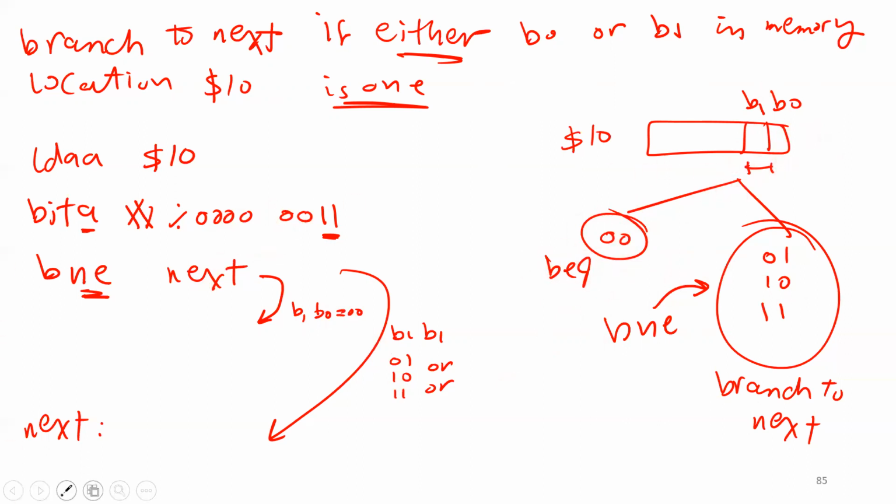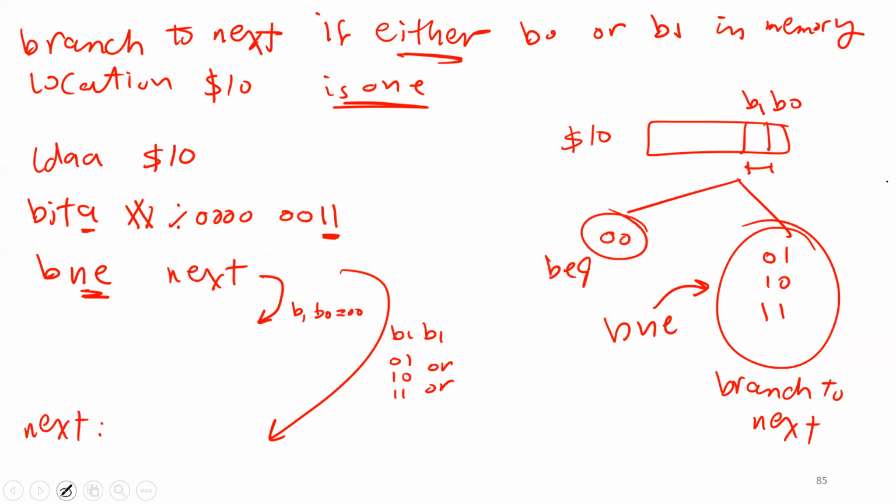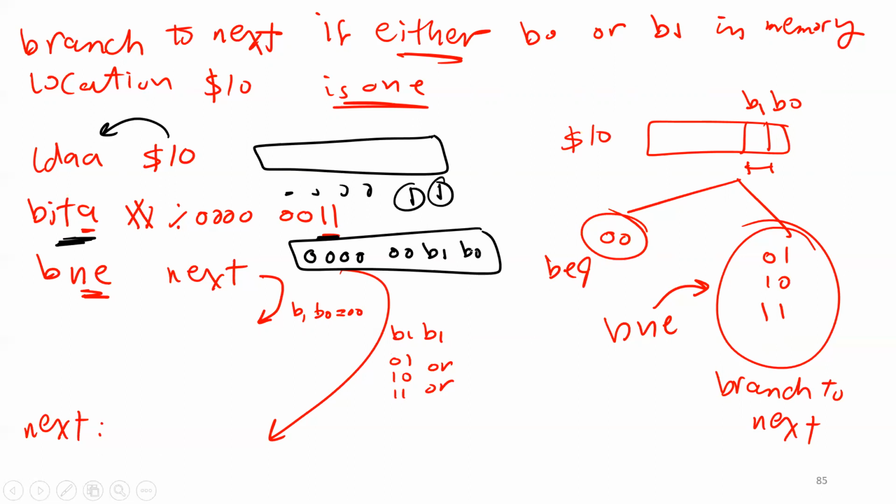Here I'm going to read the byte and do an AND operation with 1,1. I'm going to put 1,1 here, and 0 everywhere else. So the byte I'm going to get should have 0,0,0,0,0,0, and then because of the 1,1, I'm going to get bit 1 and bit 0. Is that okay? This is what I'm going to get.